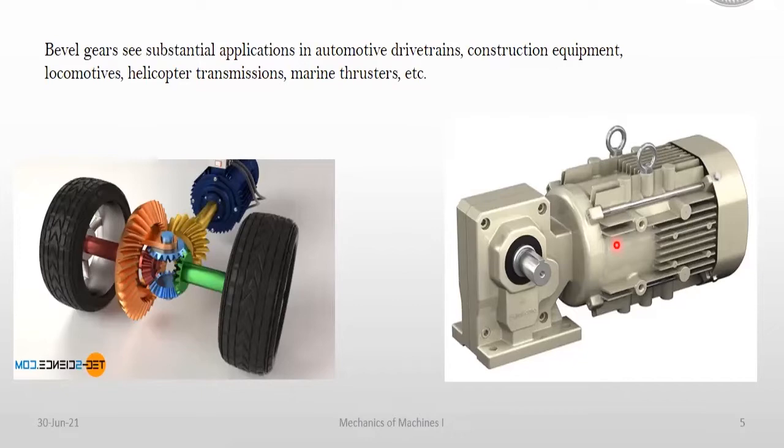It's not like spur gears or helical gears. It's quite expensive to manufacture. That is a drawback, because cost can be the determining factor in whether we can use bevel gears or another kind of mechanism. So the cost to manufacture is a big factor when you come to bevel gears.